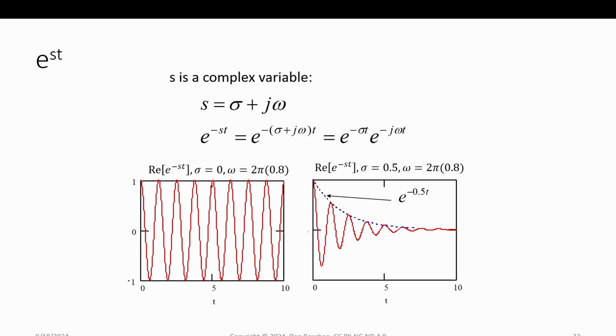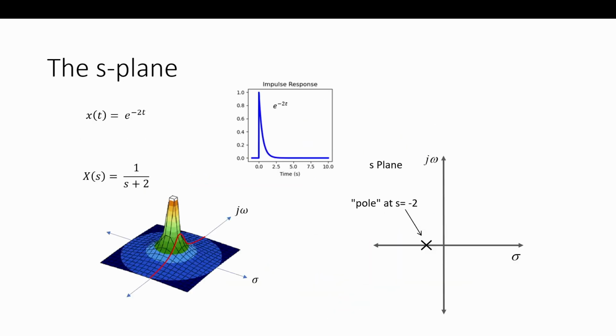So when you saw the results of that in the S-plane, you would see a pole right at that omega, which is the minus 0.5 and the j omega 2. You'd see two poles on the left half plane representing that. That's what we needed to represent it. Or in this case, it'd be a single pole. I'm sorry, there's only one fundamental component. If it was a cosine, you'd see the two of them. Let me show you another example that shows that.